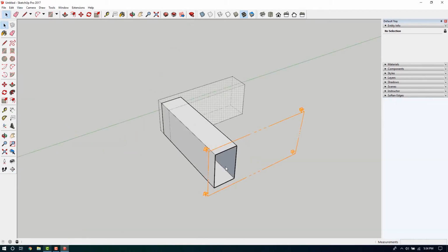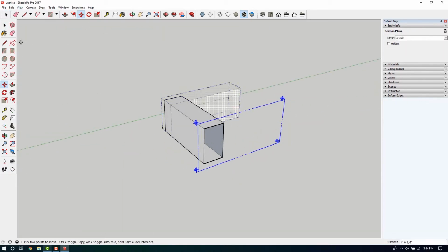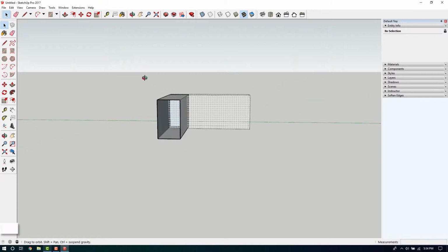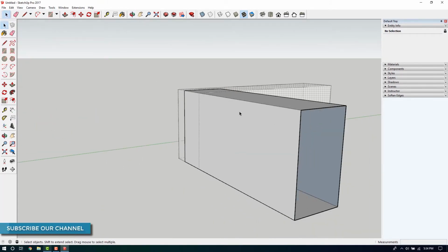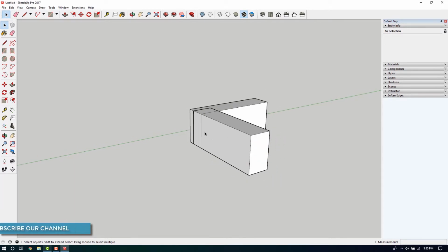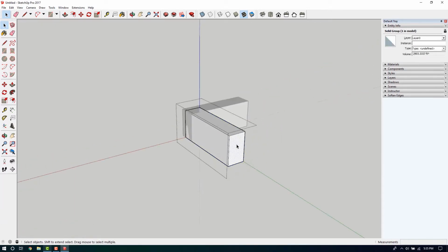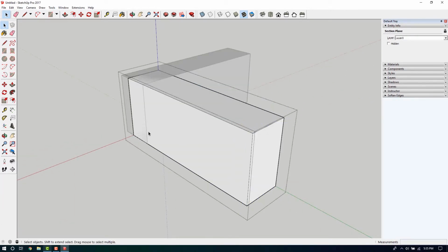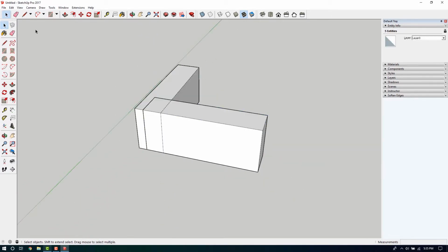Next we have the Section Plane option. First let's cut a section in the model by using the Section tool. Now if we turn off that option we can still see our section, but the section plane is hidden. We can use this option while rendering sections in Google SketchUp. Other options, axes and guides, are used to turn on and off the axes and guides.